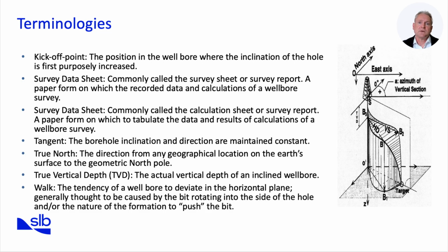It also plays a role in mud weight design, casing depth selection, and determining the well's final landing point within the hydrocarbon-bearing formation. The last term on this slide is walk. This refers to the tendency of a directional well to drift laterally, especially in the horizontal plane, without deliberate steering input. Walk is often caused by the interaction between the drill bit and formation, tool face orientation, or rotational tendencies of the bottom hole assembly.